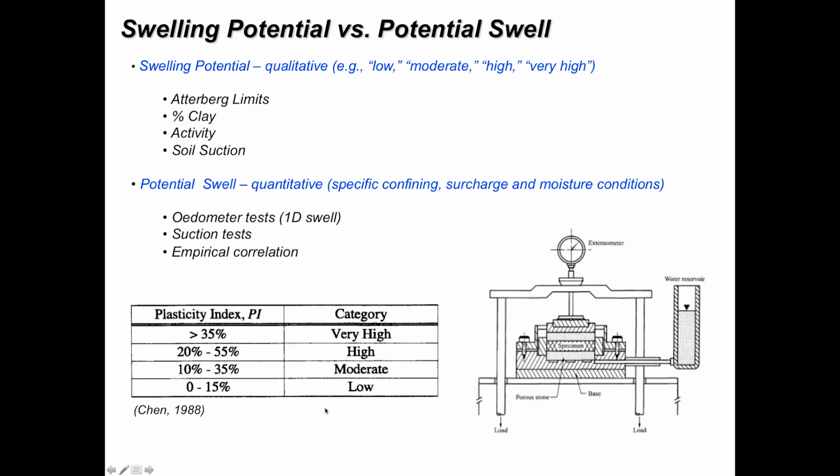And so again, what this talk is about today is, rather than using tools like plasticity index or Atterberg limits, let's advocate using approaches or clay properties that are more fundamentally related to why they're expansive. Things like mineralogy, things like surface area, things like cation exchange capacity. And so we're working on using water vapor sorption isotherms to quantify these things.